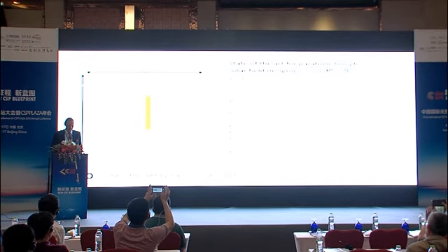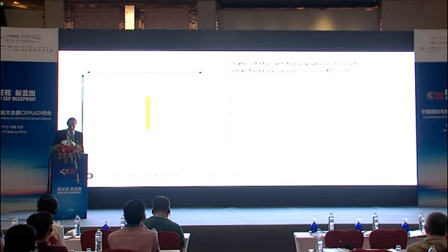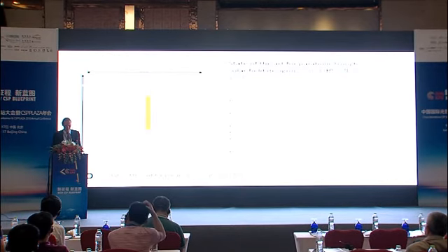What people always try to achieve is a balanced solar field. It's more or less symmetrical, to keep the pressures down, the valves efficient and the parasitics down. They always try to locate the power block in the center. They usually have wind fences on the east and west side of the solar field.